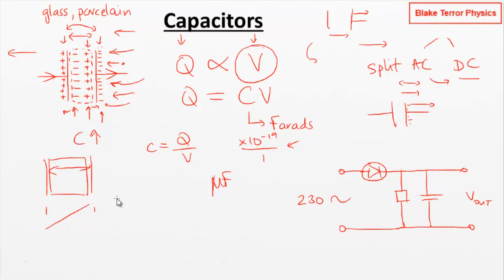So we've started off with our AC, which is doing this. We've then got the diode there. So that's our AC, we've got our diode. Okay, that line, the axis, is meant to be going through the middle. The diode is going to change that. So say we've just got the positive bits. So that's a start, but we've got these dead bits sitting here where there's nothing happening in between.